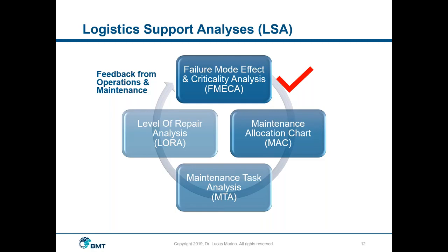Okay, we haven't done a lot of analysis here. I mean, the FMECA is a lot of work, but once we have that, we haven't really broken down the maintenance tasks yet. But we know that certain people in the organization are going to have to perform that maintenance. The electrical maintenance is probably going to the electrical shop, right? The main propulsion systems or diesel engines or electronics are going to go to those specialists. We can already determine that based on the failure mode and what we're going to have to do to fix it, type of equipment, the nature of its functions, operations, and design. So then we take those tasks and we're going to break them down, and that's what's next.